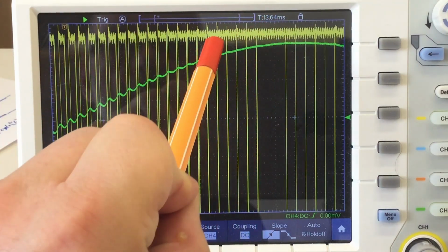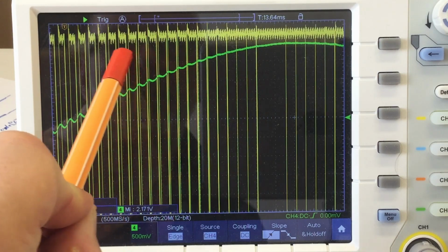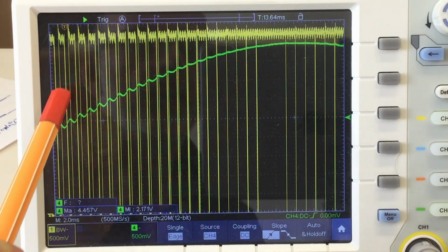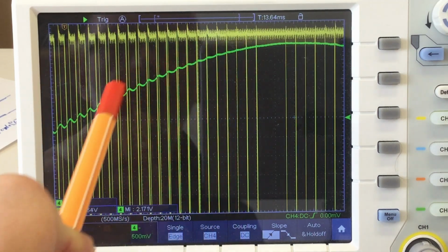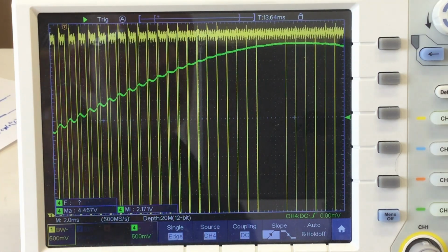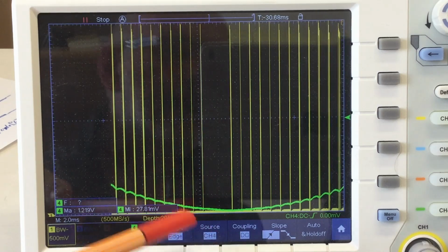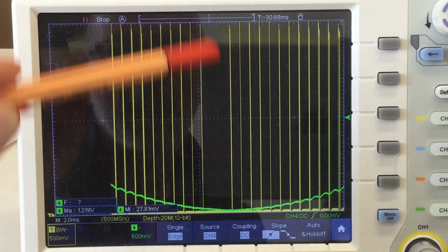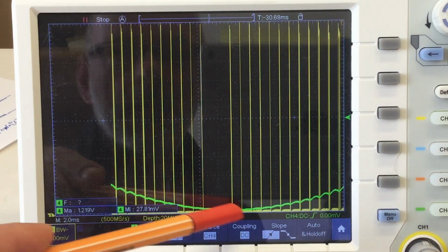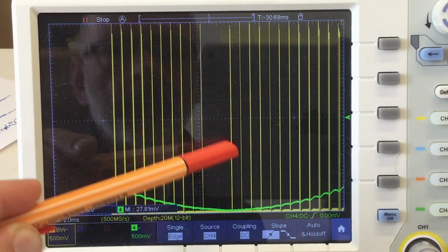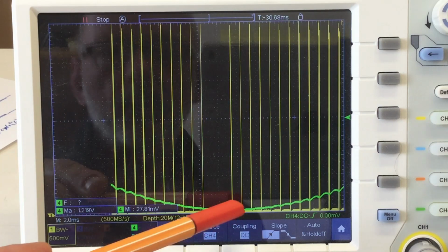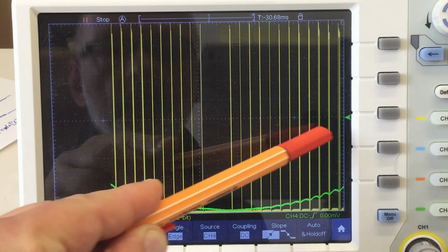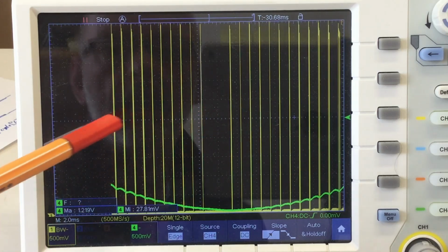And before that, you see that the duty cycle is still quite high, but it's decreasing here to the left, as is the analog value. Accordingly, at the lowest point of our sine wave, our PWM signal is for a short time always off, and you see to the left and the right where our analog signal is rising again, the duty cycle is slowly increasing.